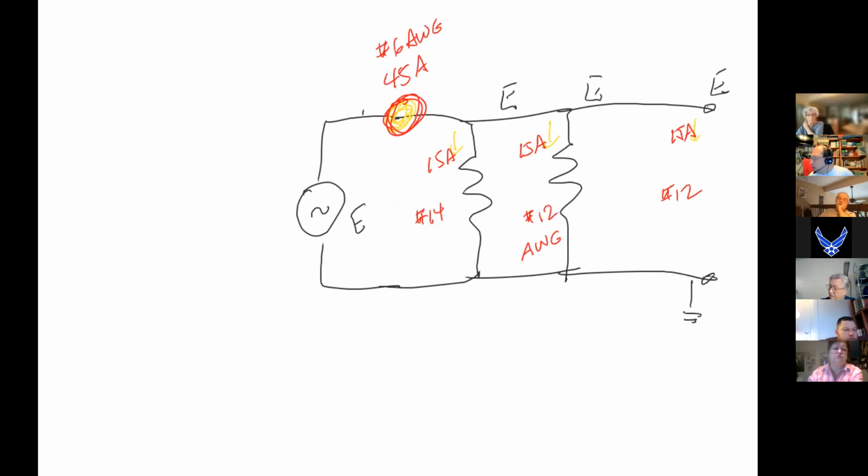And some houses might have enough of them that your main circuit breakers, the actual bus, is set up for 200 amps. At that point, that's not even usually a piece of wire. That's usually just a solid bar of copper. And the wire coming in from the utility might be like 3/0, which is a very, very heavy cable.